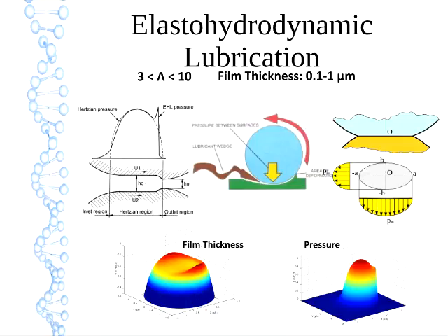and why it's called elastohydrodynamic is that the elastic deformation at the contact is significant relative to the film thickness. Before this regime was actually discovered, people could not figure out why these contacts did not fail, because they were calculating the lubricant films as less than a micron thick.